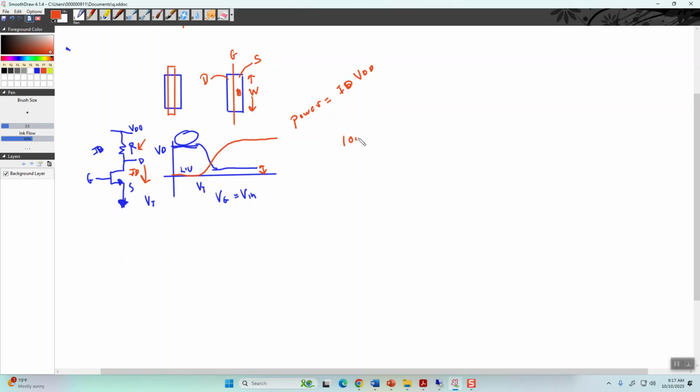if you had 1,000 inverters on your chip, right? And the probability of low, right down here, we could say is 1/2. That means 1/2 of these inverters are burning a lot of power, doesn't matter the clock speed or anything. You are just burning a lot of power, right? And just as a prelude, static CMOS will solve that problem.